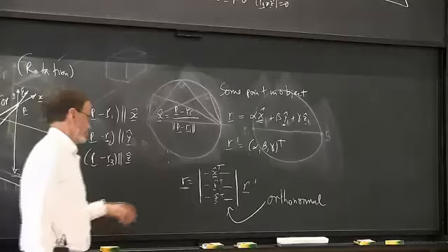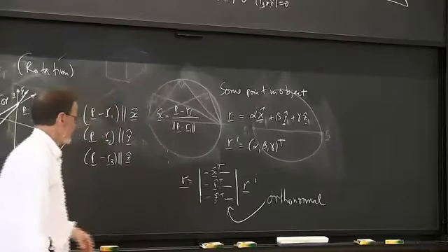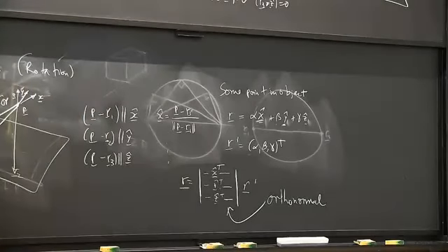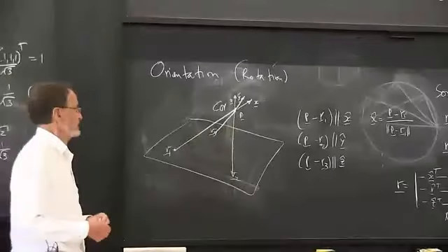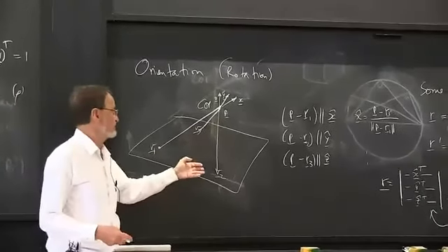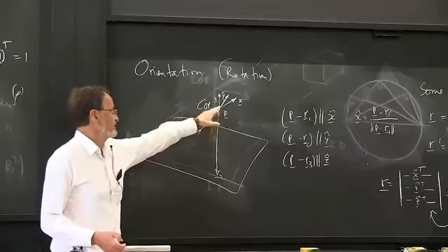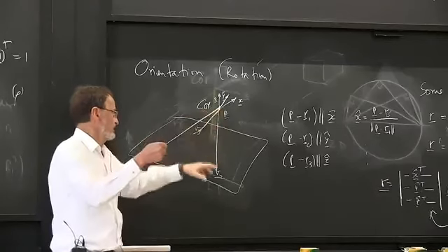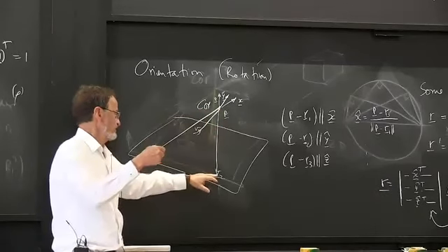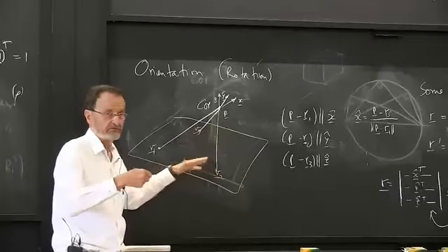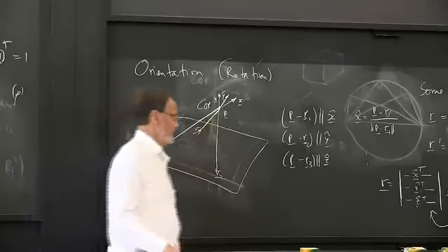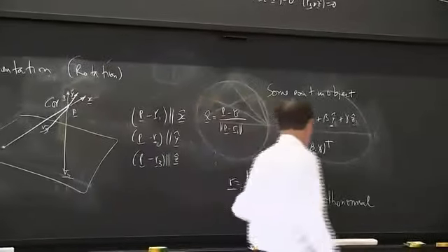quite a few photogrammetric tasks involve finding that matrix. And in this case, we were able to do it rather straightforwardly because we explicitly could determine the direction of the coordinate axes in the object, written out in terms of the coordinates of the camera. So, okay. And of course, if we want to, we can invert this.